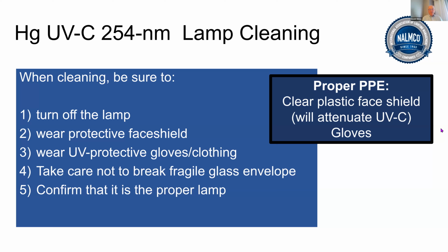misuse of the germicidal lamp. But you also need to be sure that your lamp is actually emitting in the UVC, and you will know that if you do a quick measurement check to make sure that you have an effective irradiance in the upper room. It goes without saying that in dealing with a fragile glass envelope lamp, you don't want to break it.